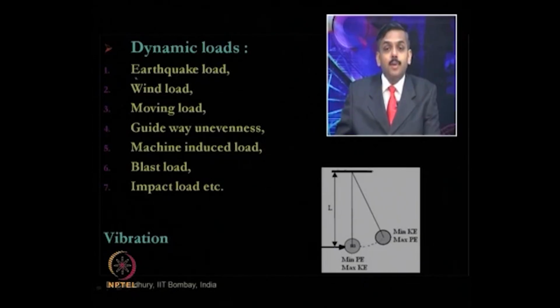But there are a few time dependent loads, that is, which vary with respect to time, but still those are not dynamic load. For example, suppose in the construction or excavation period, like at the starting of excavation and end of excavation, there is a change of load due to the taking out of the material from the ground with respect to time. So, with respect to time the load has changed, but it is not a dynamic load because it does not create any vibration in the system.